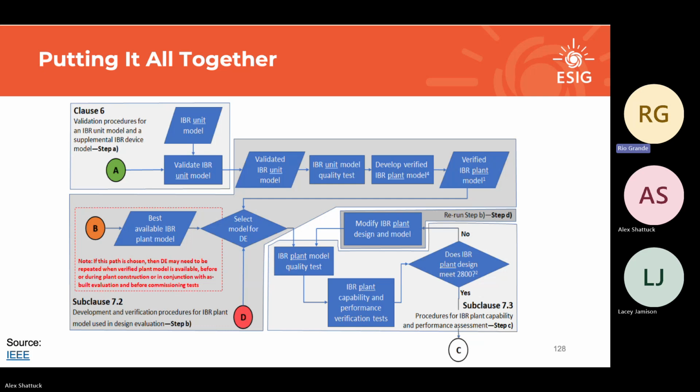So this happens in ERCOT quite often because, one, they have advanced procedures, and two, because it's a complex system, right? So if you look at ERCOT's DWG manual and the performance requirements for it, you read things like maximize reactive power response, respond immediately, 90% of your whole response in less than a second. They want a really aggressive, really strong, accurate response. That goes like we saw yesterday, that tuning does not work in a weak grid. Or that tuning might not work in a SSO, SSR situation.